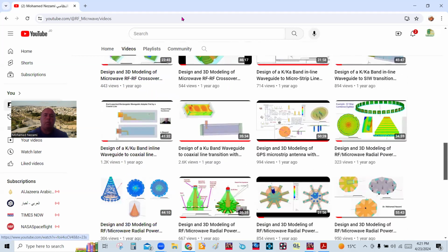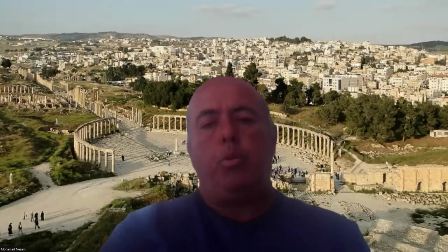Okay, again, I would like to thank you all for having put up with me on this series of flat or planar antenna feed networks. We've covered networks that were based on the T-junctions, and then other networks that were based on the Wilkinson dividers. These are the most common two, and I showed some examples of how you would do this for some mixed network feed lines.